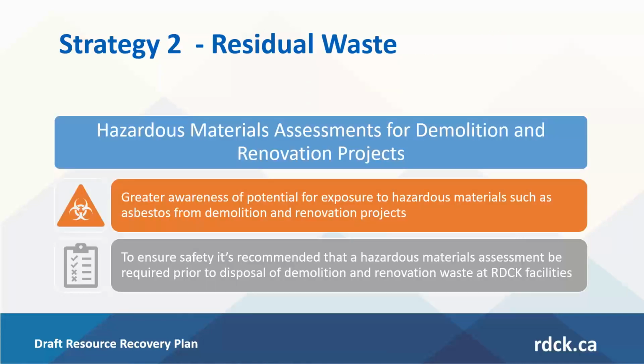The second action in the residual waste strategy is hazardous materials assessments for demolition and renovation projects. There is a greater awareness of the potential for exposure to hazardous materials such as asbestos from demolition and renovation projects. So to ensure safety, it's recommended that a hazardous materials assessment be required prior to disposal of demolition and renovation waste at RDCK facilities.